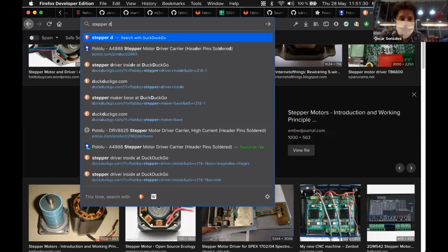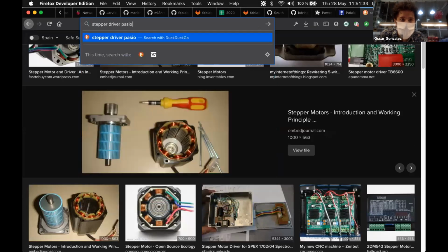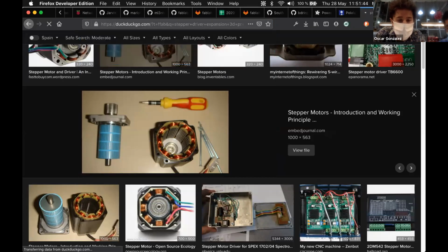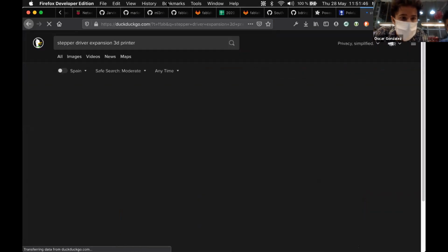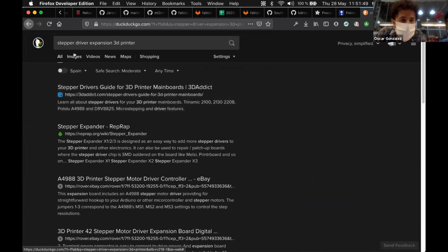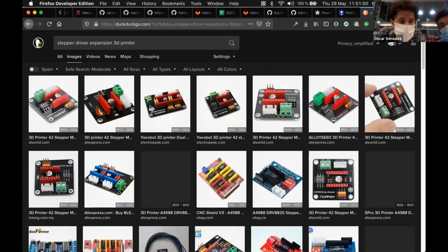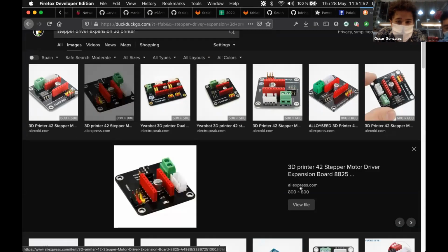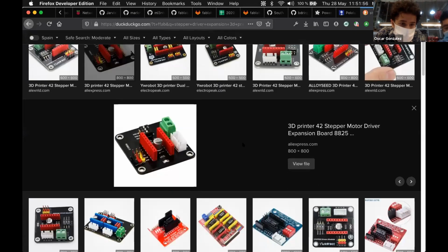That is actually common in the 3D printing world. If you want to use, for example, dual core extrusion, most of the machine boards don't accept more stepper drivers. So they actually sell this kind of small PCBs that you just need to connect to 3 digital pins, and they will enable you to have another external driver outside of the board without having to modify the main board.